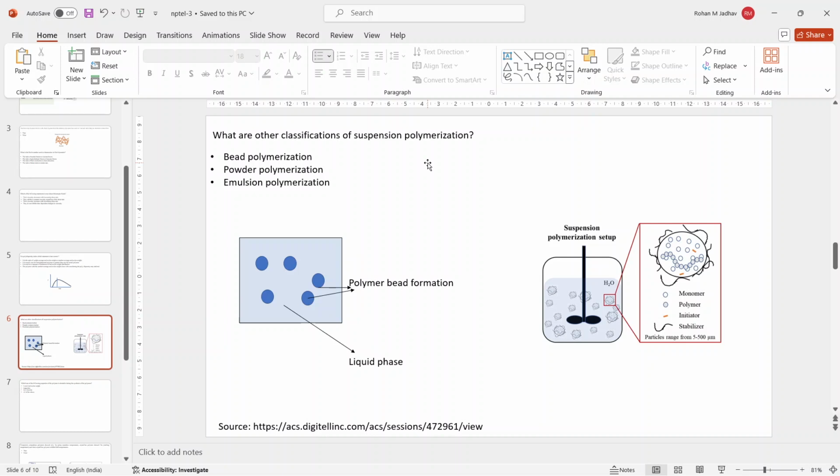So, mechanical agitation or any kind of impelling force is used to mix the monomers, usually in the liquid phase where they are suspended and you are reacting them. The liquid phase is used basically to increase the handleability of the polymer since it becomes extremely viscous once it is polymerized. And the temperature increase during polymerization is also very prominent. And to control that, you can also use the liquid. So you have the liquid phase and you are polymerizing in that. And once the polymer is formed, it forms a suspension.